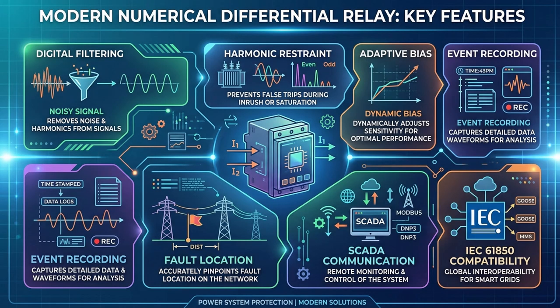Modern numerical differential relays do much more than just trip. They perform digital filtering, harmonic restraint, adaptive bias, event recording, fault location, and even communicate with SCADA using IEC 61850. Smart, fast, and highly reliable protection.